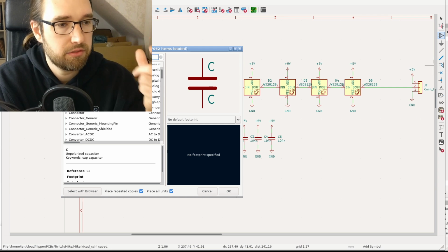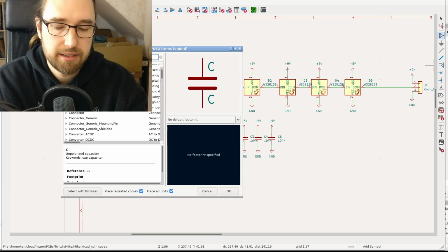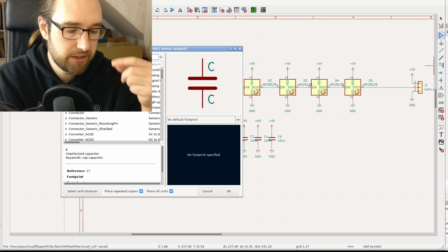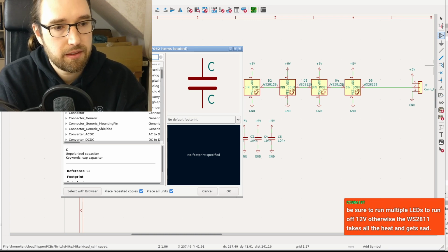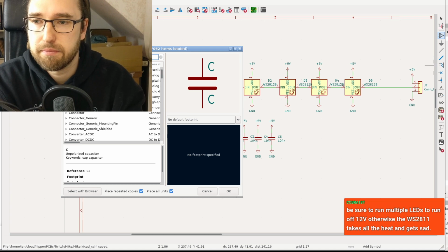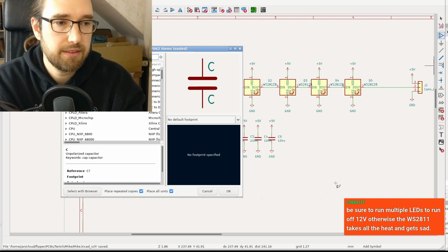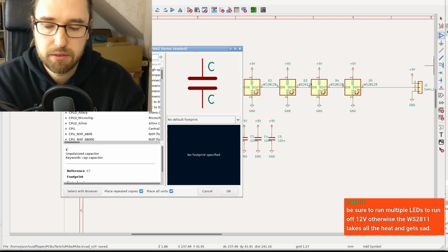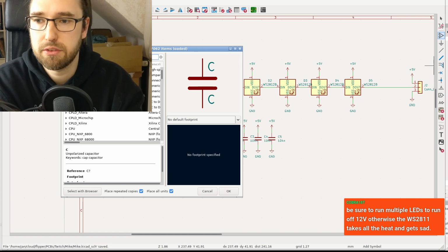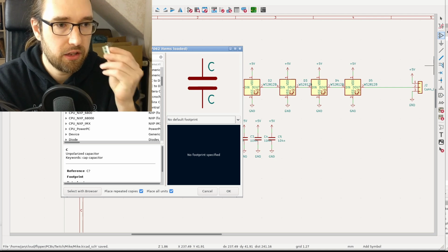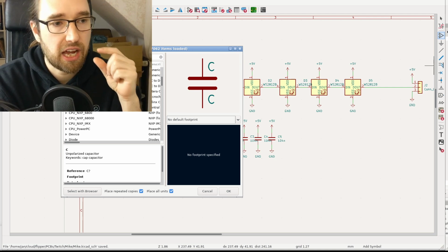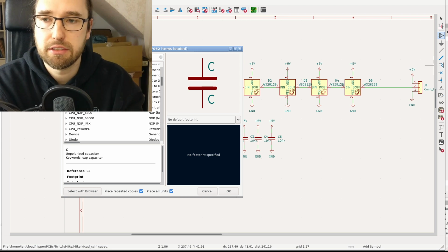a board like the PD LED from Multimorphic or any other LED controller. It works similar to this WS2811 chip, right? Yeah, you're right. So Cora's right. Do not run a single LED off 12 volts. That's not so good. But basically the PD LED works similar to this chip. It controls a lot of LEDs in parallel, and it's current controlled per LED. So it's a fixed current, and you can also do that.